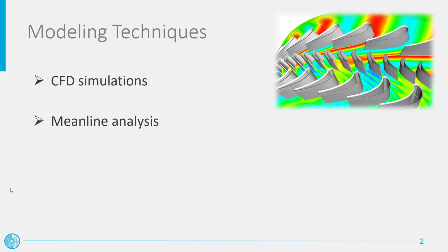A modeling approach which entails a much lower computational cost than CFD is the mean-line method, where a turbo machine model is formulated with a lumped parameter approach, only focusing on inlet and exit conditions of each blade cascade, regardless of the detailed shape of the blade. At the considered locations along the machine, uniform and unidirectional flow is assumed.